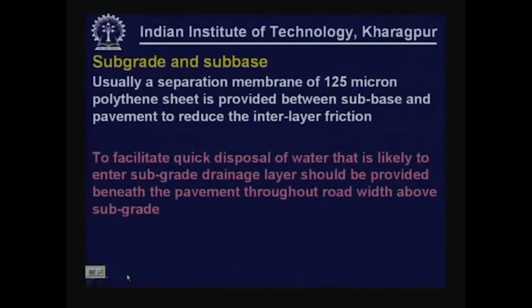Also, to facilitate quick disposal of water that is likely to enter the subgrade, a drainage layer should be provided beneath the pavement throughout the road width above the subgrade. If there is a significant requirement of drainage, a drainage layer over the subgrade can be provided.